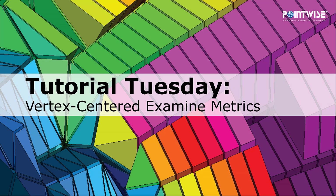In this video, we demonstrate how to use the 3 new Vertex-Centered examine metrics that were added with the release of Pointwise version 18.3 Release 2. These metrics will be particularly useful for assessing mesh quality if you are running a Vertex-Centered solver, such as NASA Fun3D or ANSYS CFX, among others.